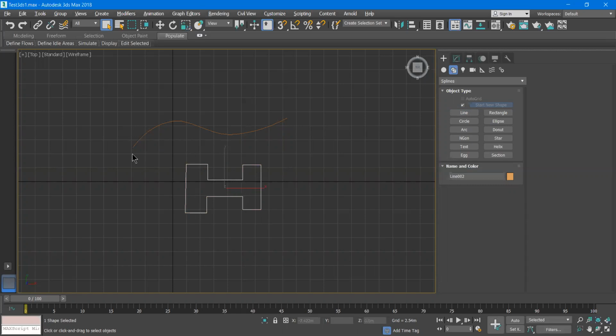I want a wall to run from this point to the end point on this line, and its shape must be like an I section. Our aim is to draw a wall over this path, but it must have this I shape. So to create a 3D wall with a shape like this onto this path, we need the command loft.